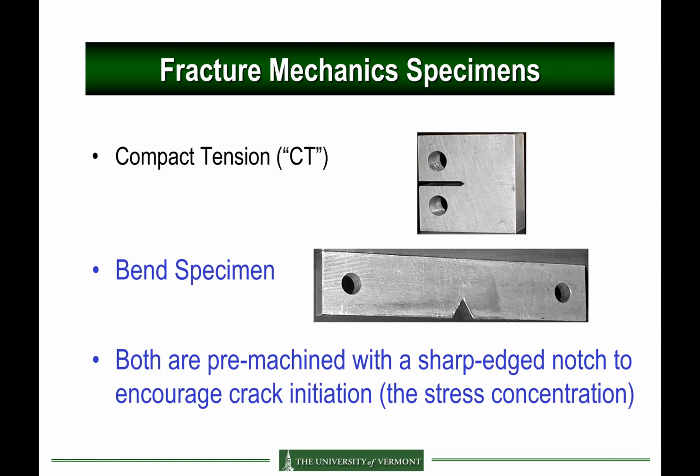All right. So now, this was for Charpy. This is not what Lab 6 will use, because the Charpy analysis, unfortunately, is not very predictive. It gives you just a temperature, but in terms of design, does not give you any idea of stress or strain, and does not even include really a crack in the beginning. It's just a notch.